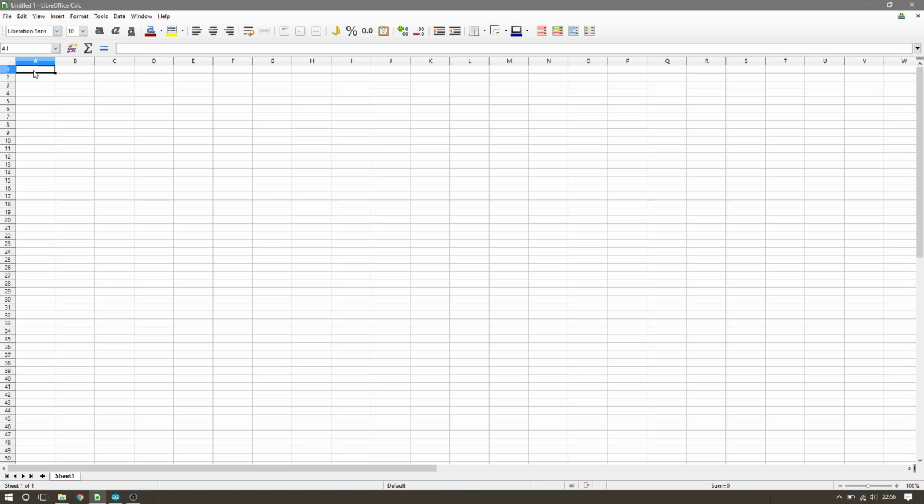Now, I'm going to be using an RC circuit to compare it. And each one has an orange resistor, so a 33k resistor, and then per set of capacitors, all of them are matched 220 microfarad 50 volt electrolytic capacitors, and they are charging with 1, 2, or 3 33 kilo ohm resistors. And we will be doing a 1-minute